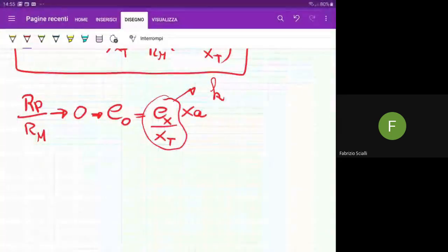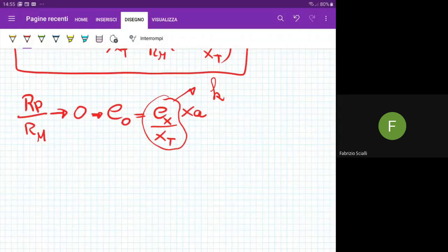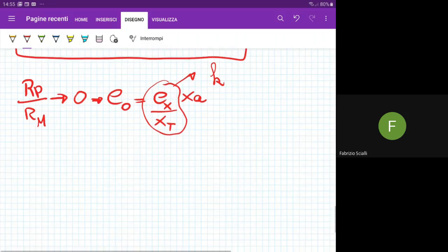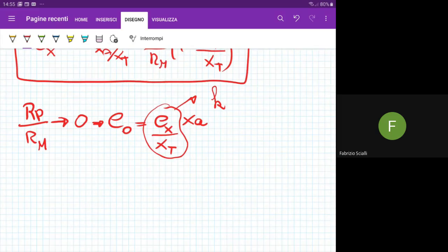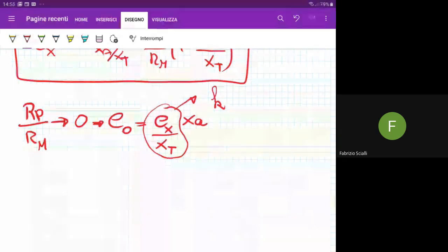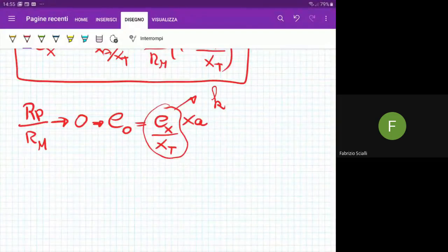Even when you say larger, like if it's 1 ohm larger? One order of magnitude. So, 1 or 2 orders of magnitude. If my potentiometer resistance is, let's say, 2 ohms, and your measuring device has 200 ohms, then it's not bad. If you have 2,000 ohms, much better. So the reference is important.